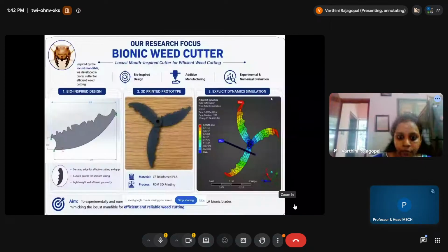Some may say that FDM is also known as triple F, that is fused filament fabrication, right? So in the name itself, there is filament. So let me ask my question like this. Do you think FDM can print using only filaments, or can I have raw material in a different format? Can it print only filament, or can it print any other form of material? No. Yeah, actually it can print other materials also. You can have a paste type of raw material. In order to print food materials, you can use paste.